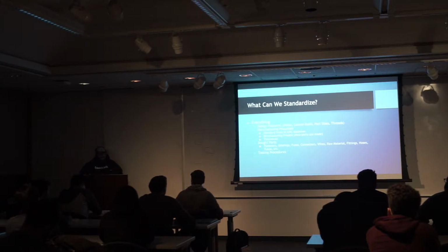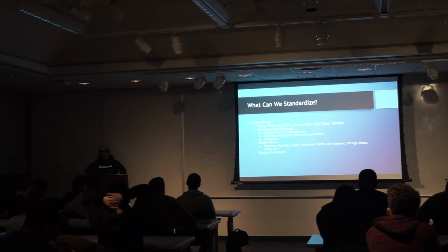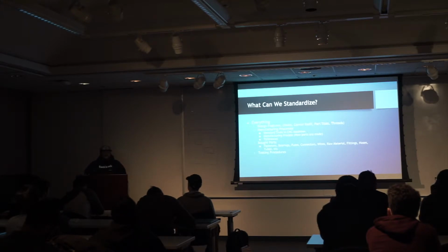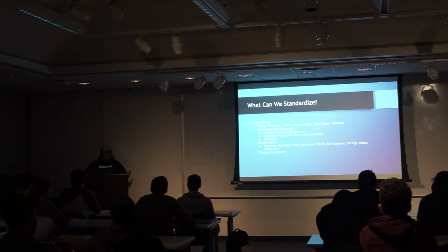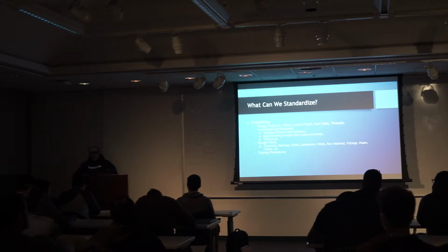You can standardize manufacturing processes. So as we talked about, you can standardize the tools in a CNC machine. A lot of our parts kind of look the same: semi-prismatic, some holes, maybe some bearing bores. So the way you go about making those, you can standardize, right? You face it, then you drill the holes, and you mill the features, or whatever. And then tolerances for pins, press fits, clearance holes, those are all standardized as well. And then obviously bought parts.